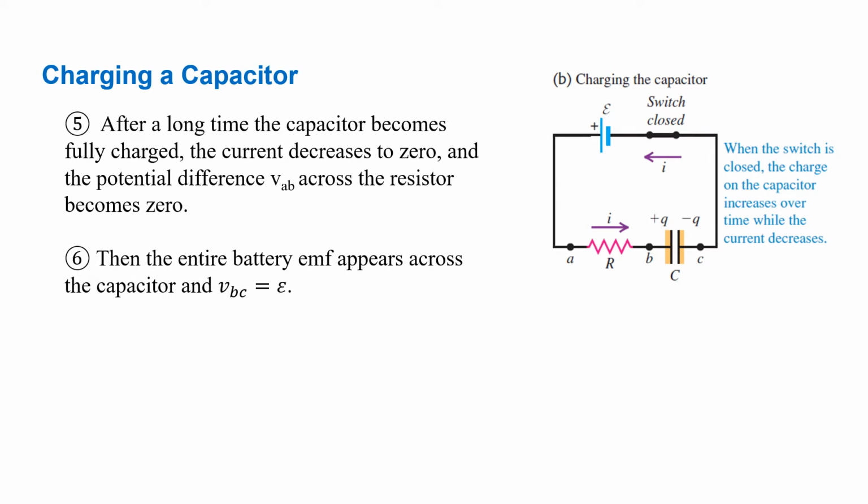So let's review for a while. At time equals 0, there is no charge in your capacitor. So in that case, your capacitor actually acts like a short circuit. It's just like a wire here.